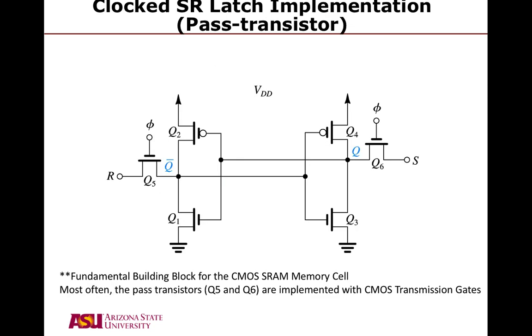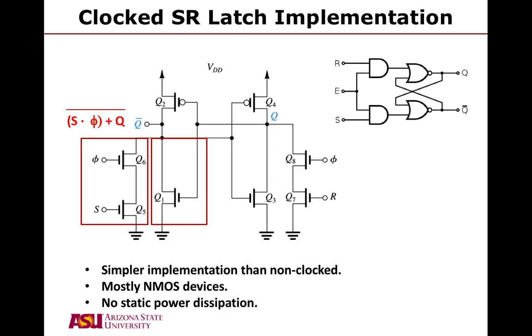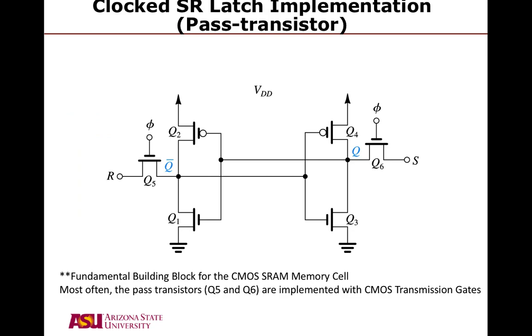Okay, so then what happened? Well, this is still too many transistors if you're going to do these in the billions of memory cells. So again, over time, it has been further simplified. So now we still have our 2 inverters. You can see Q bar supplies one inverter, output Q supplies the left-hand side inverter, which then of course gives you Q bar. So these are the coupled inverters.